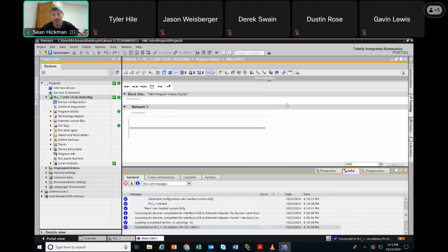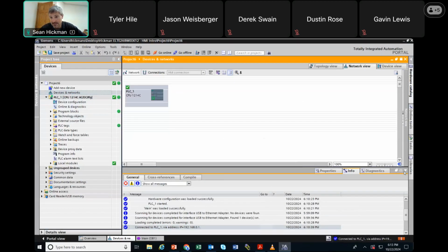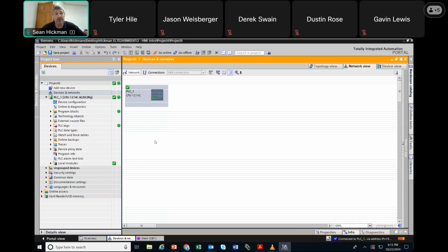Yeah, you're going to spend a lot of time right here on this page. If I click my devices and networks here, see it spins for a little bit and then it pops up. I got some stuff going on here. See all this stuff I got going right here? I'm going to kick that down. This is my PLC. When I add HMIs and stuff like that, this will show me the network, because this little green right here will be connected to the green of the HMI or the green of the next PLC, the green of the VFD or whatever like that. It kind of shows you pictorially your little network there.